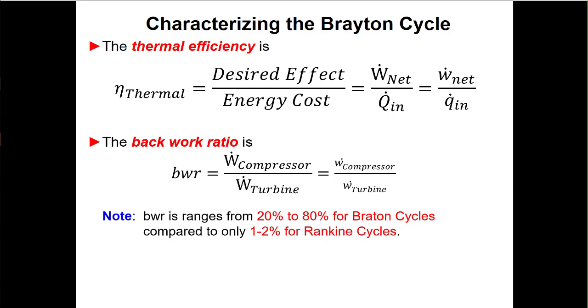And that's because, remember that part of the benefit of running the Rankine cycle was that it's comparatively easy. It doesn't take much power to increase the pressure of a liquid, right? Because it's incompressible, right? But compressing a gas is hard because those gas molecules will kind of scrunch up, right? So it takes more power to increase the pressure of a gas versus a liquid.